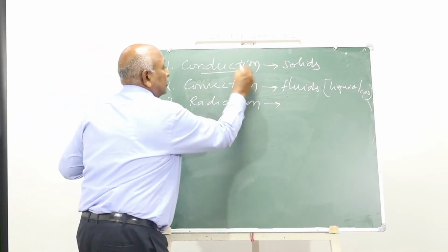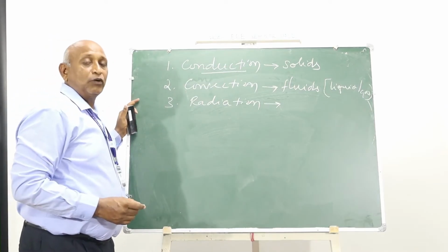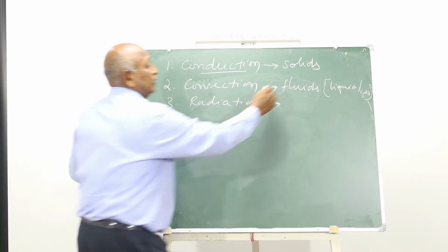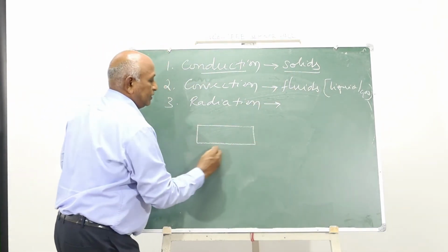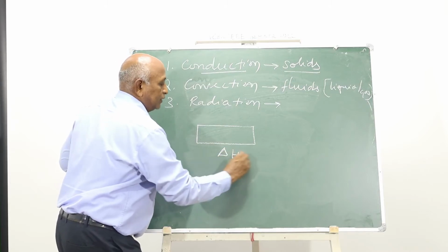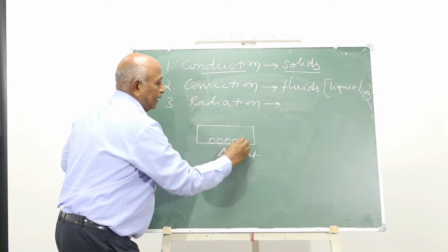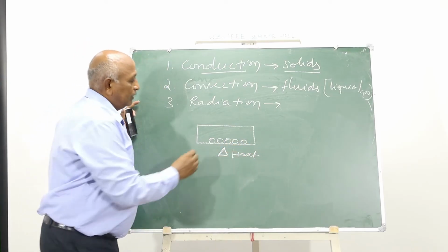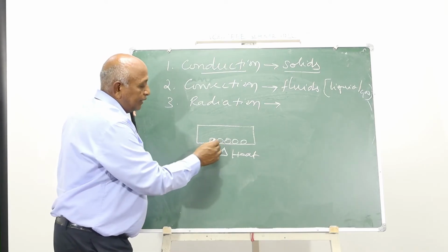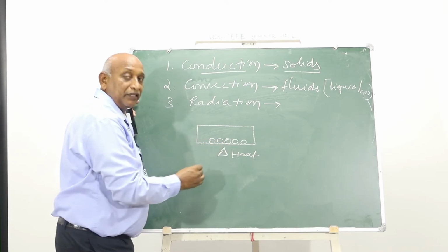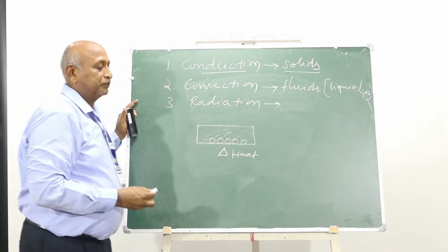First, I'll tell you what is conduction. Conduction heat transfer. The medium required for conduction heat transfer is solid. In solids, when the solid material is subjected to heat, the molecules present in the solid material attain thermal energy. Due to the thermal energy, these molecules vibrate and the heat transfers from one molecule to another molecule. Likewise, the whole solid material gets heated.